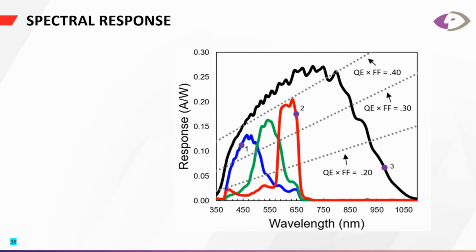Thank you, Matthew. Spectral response is very important. When looking at the EMVA 1288 data sheet, we get a quantum efficiency value, but this is at a particular wavelength. For mono, it's just using the green wavelength. For color, we get one for each color channel, but we want to see how this may vary across the entire spectrum. So we use an additional test to measure how the camera responds per wavelength of light. When we do this, we also consider the pixel area in this measurement.